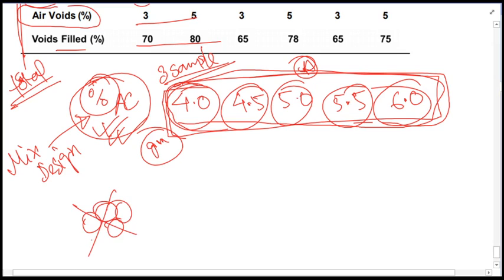So just bring another sample and do another sieve analysis of aggregate; a different grade of aggregates needs to be used for the construction of this particular pavement. Other than that, it will not be satisfied. So if not satisfied, you will have to change the gradation of aggregates.